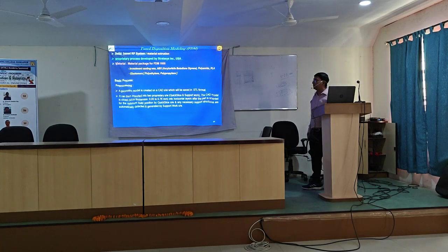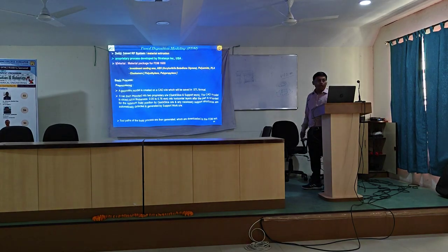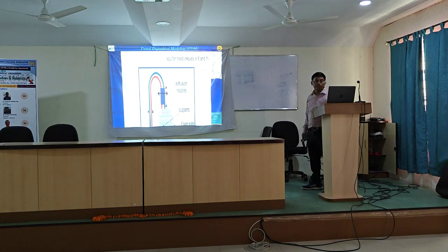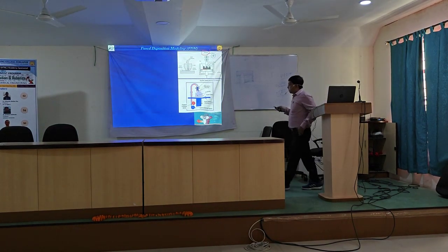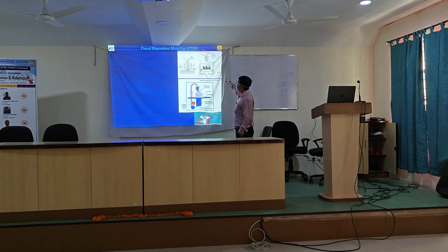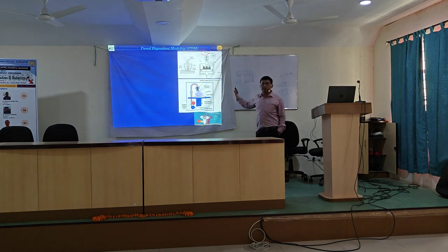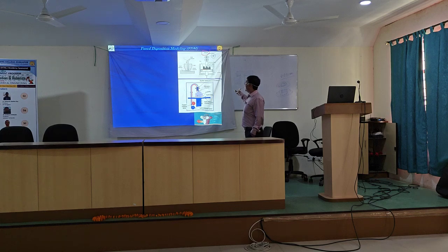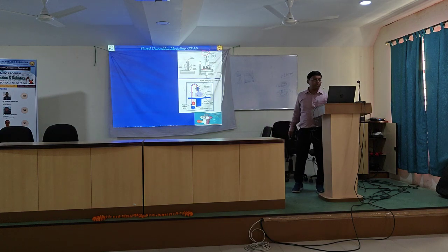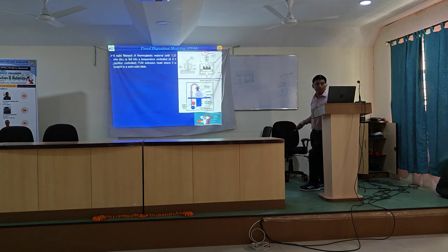Again, your basic thing is pre-processing. After pre-processing, you have to do the main process. In this case, this is the platform, this is the extrusion head. Extrusion head is temperature control and position control. That means XY movement is there in the extrusion head and Z movement is provided in the build platform. Now there is a set of rollers and this is the input material, the feedstock. Feedstock is in filament form, the polymer filament. So filament is either made of PLA or ABS or many other materials available nowadays.